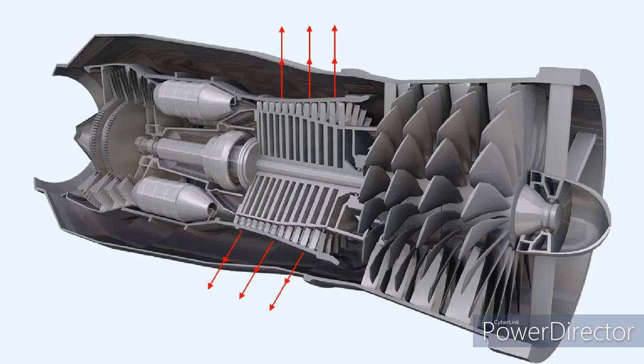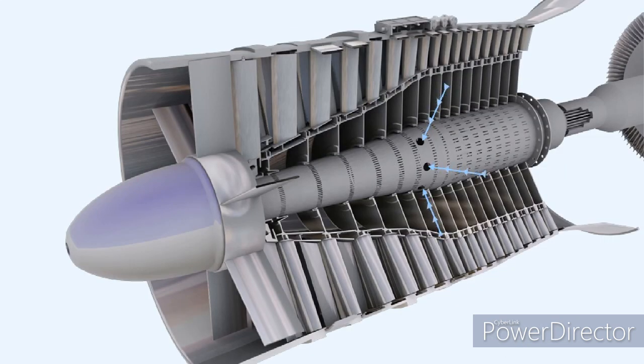The inside of a gas turbine engine is, understandably, very hot when the engine is in operation. Air, bled off from various positions on the compressor, is used to lower the temperature of those internal parts of the engine which may suffer from excessive heat. The pressure of the air which enters the engine is raised considerably as it passes through the compressor, and it stays reasonably high as it goes through the turbine assembly.